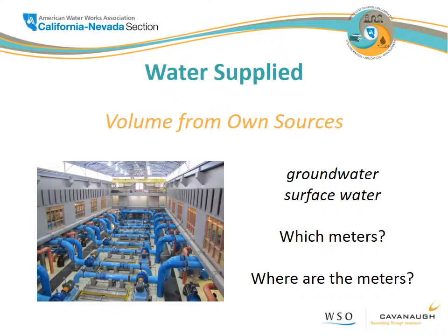Because it's important to remember that data is generated from these physical processes. Meters are instruments that are tangible and real, and even getting eyes on meters can be an important process of evaluating their reliability. We see a lot of meters that aren't set up for success because they come just after a bend or they're placed really close to a pump. So it's important to qualify the quality of data that comes from a meter that's not set up for success, and understanding where they are and which volumes they're tracking is a key part of that.